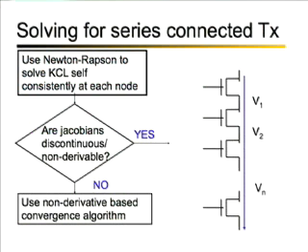The next important thing that one has to think about is how to simulate stacks. So let's say I have a stack of transistors which are essentially series connected transistors, and the idea is to find out what these intermediate node voltages V1, V2 up to Vn are. And the important constraint here is that the current has to be continuous. So we have to solve for current continuity and at the same time figure out what these different voltage levels are so that we can solve KCL efficiently at all these different nodes.